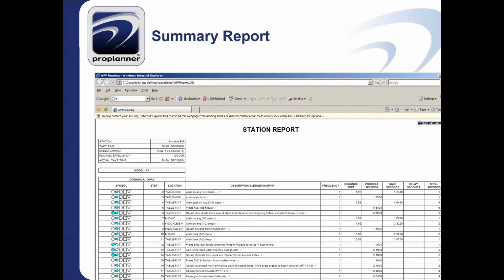So this allows me to take these different steps, identify the process symbology, and where they're performed, and this is just a user-defined location. It's essentially going to be represented in the AutoCAD drawing as a text label on a certain layer of AutoCAD. So table-hub will be an AutoCAD text object in the drawing on a certain layer.